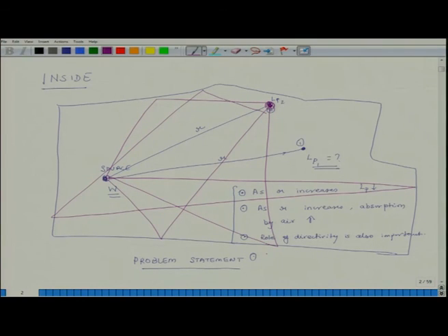That relation accounts for all these effects, the role of R, the role of sound absorption by air, the impact of directivity, but it also accounts for reflection of sound, because the sound which is being received at the point of interest is partly direct in nature and it is partly reflected in nature, and we have to account for both of those.